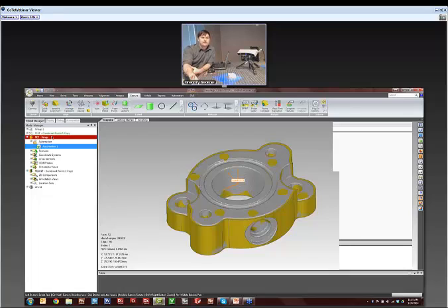But if you switch over to the HDR mode, it actually gets pretty good data, and I've had some good success. Honestly, the best way is to have your regional manager from 3D Systems scan a sample part. That's the only way for us to really get a good idea of how well it scans that exact surface finish, and provide you with the sample to see if it meets your expectations.